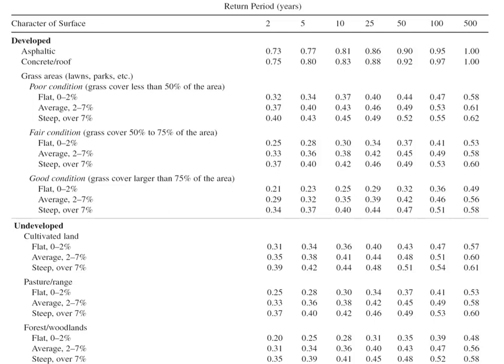So if it's blades of grass, a really steep slope, then there's going to be more of the tendency for that rainfall to continue over the surface than be bound to the surface of the blades of grass. And there's less time for it to infiltrate. And so the trend is steeper slope leads to more runoff. A flat slope allows infiltration. Water can puddle, and puddles help to force the moisture underground. A pool of water is going to increase the hydrostatic pressure, forcing the water through the soil grains and into the ground. And so if it's flat, the puddling and the pooling can occur.